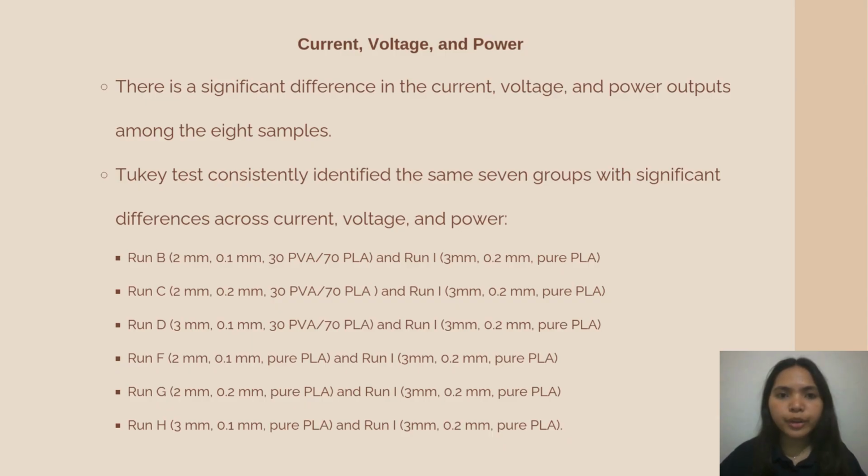Run I outperformed the other configurations, showing superior outputs due to its optimal combination of pure PLA, 3 mm thickness, and 0.2 mm resolution. Comparisons among the remaining samples showed no significant differences, highlighting that variation in material and print settings alone were insufficient to achieve similar performance.